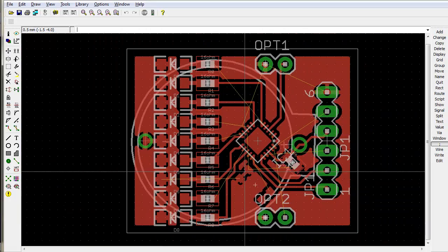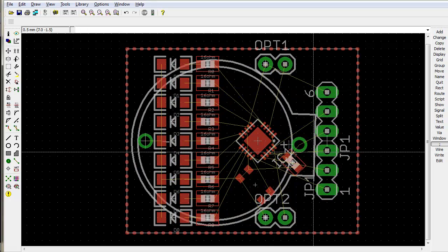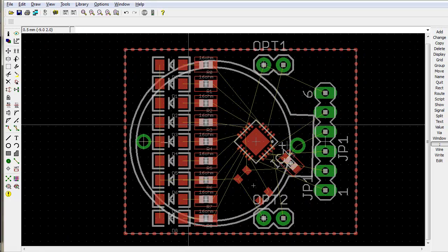It's just not going to happen. So that's the reason that we don't use the autorouter in that way. I'm using the rip command now. Rip star means rip up everything. So all of it goes away, all that hard work the autorouter just did.